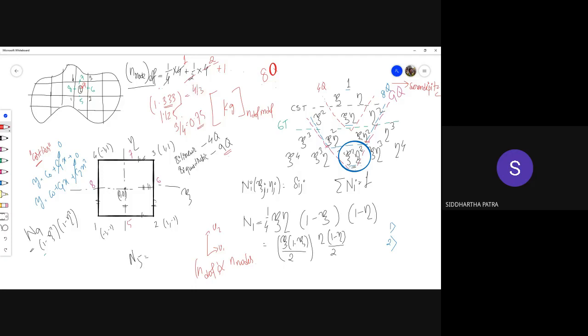So you get to use quadratic shape functions, in some sense quadratic, with 25% lesser number of nodes. It's kind of like a 25% discount. Hence the term serendipity. But obviously in mathematics there is no free lunch, and you also pay the price for getting quadratic shape functions at 25% lesser number of nodes. There are issues called overshoot and undershoot.